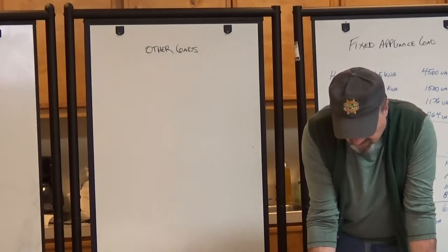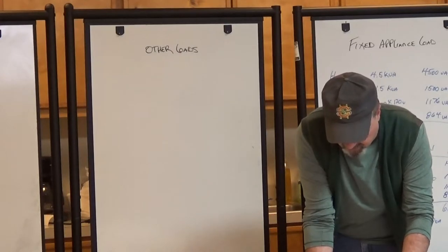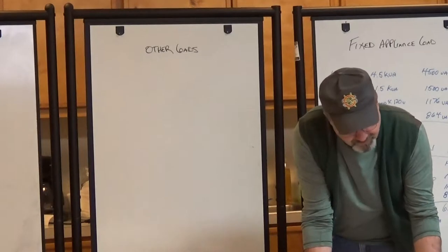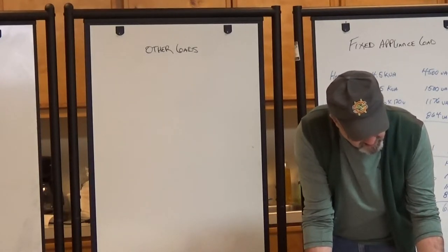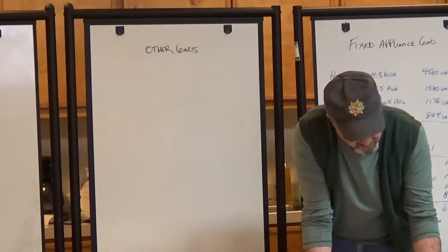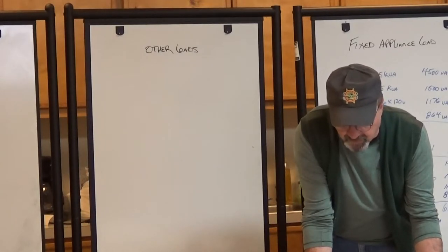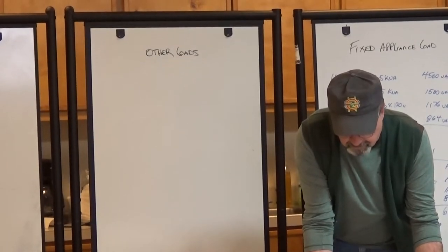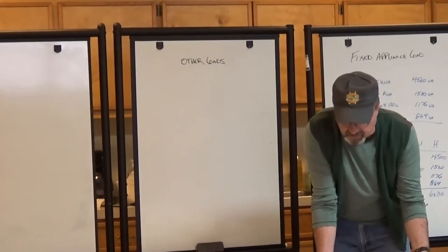And so when you look through A through L, it's talking about electric dryers, electric cooking appliances in dwelling units, and motor loads, luminaires, heavy-duty lampholders, signs and outline lighting, show windows, fixed multi-outlet assemblies, dwelling occupancies, banks, office buildings, and other outlets, okay?